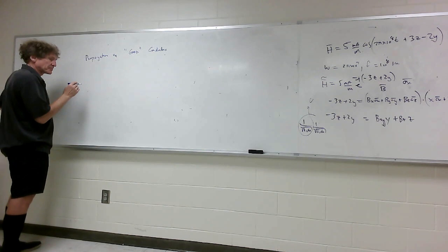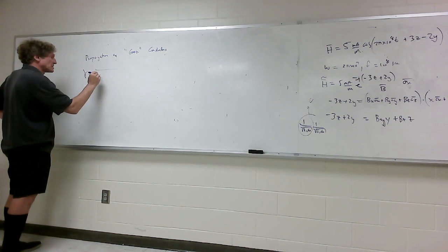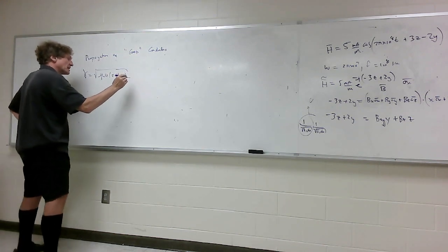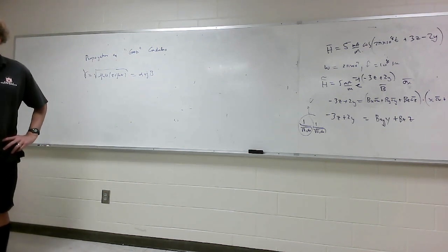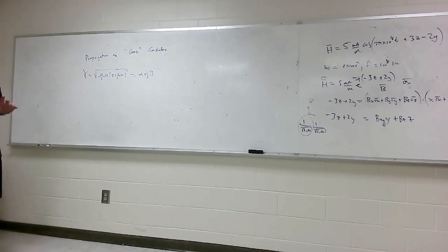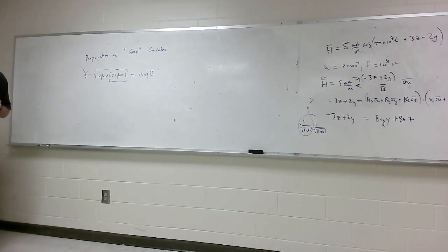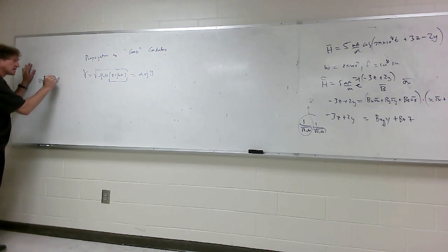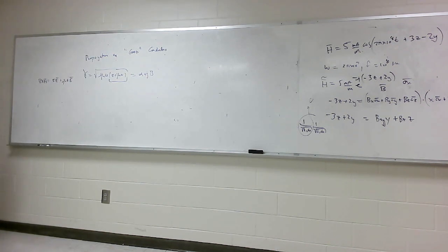If you think about the actual value gamma, it's equal to the square root of j omega mu sigma plus j omega epsilon, and it's equal to alpha plus j beta. Are you with me? Now, if you look at this, sigma and j omega epsilon are the coefficients of the E field when you do curl of H. So curl of H will have sigma E plus j omega epsilon E as the two terms. Do you all remember that?